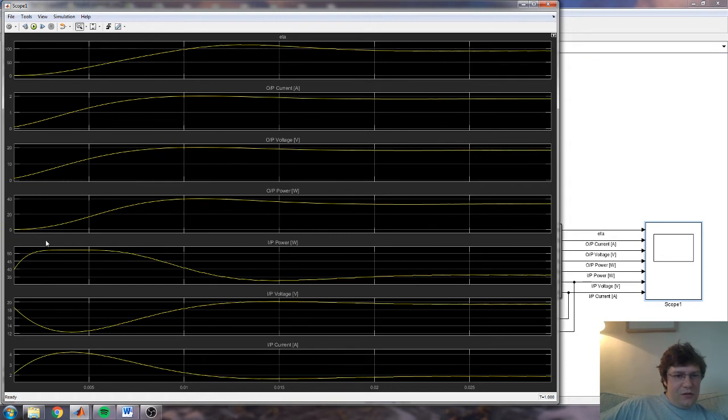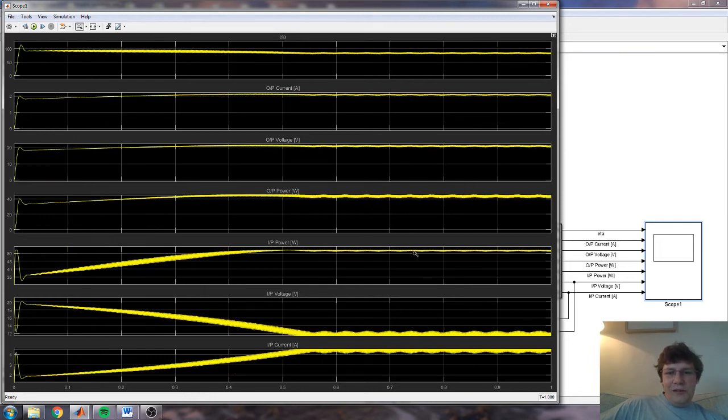Yes, loss of energy entering the system here, and no energy leaving, so plenty of energy stored in the system at this time. Energy not coming in so much now, but energy leaving. Because this calculation of efficiency is based effectively at every instant in time, we are getting something for nothing at this instant, which is why we're above 100. If we did an integrated energy approach, that wouldn't be wrong, but when we look at steady state, where the input and output powers are not changing very much, this calculation is good enough.